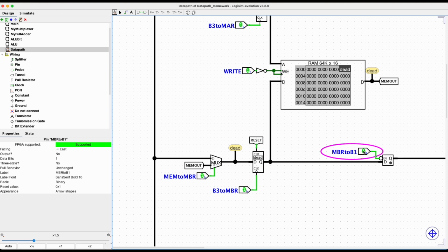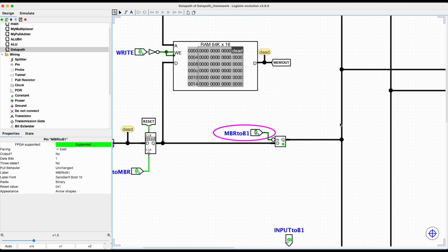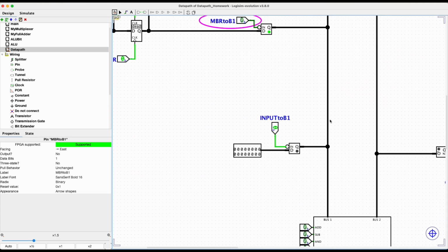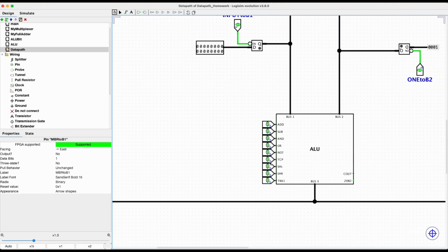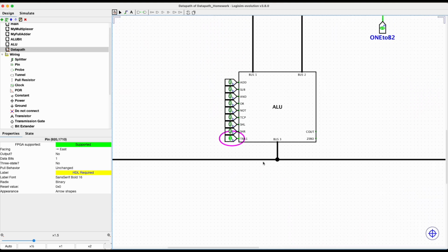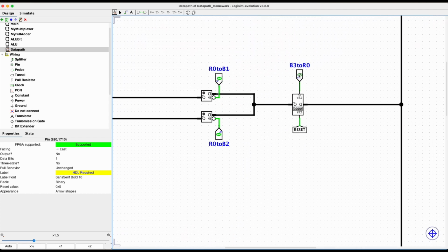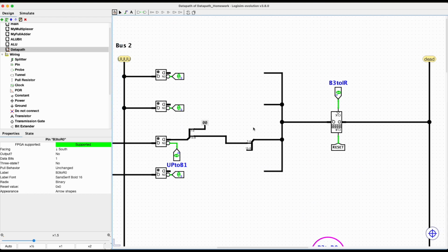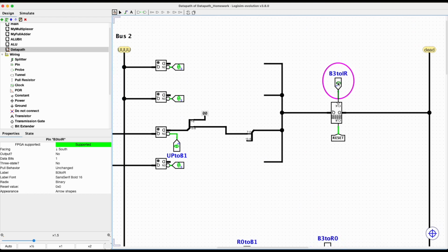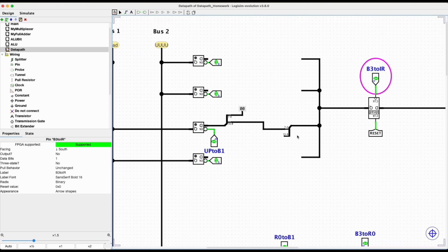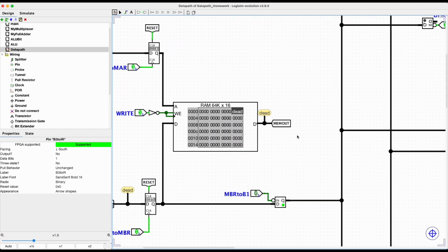We'll put that onto bus 1. So now DEAD is coming out onto bus 1. That's our instruction, our pretend instruction. We'll turn on TRA1, so we got DEAD out onto bus 3. And go ahead and clock that into your registers here. Do it for all 4 to make sure that all 4 registers work. And then last but not least, your instruction register. So now we have DEAD coming out of our instruction register right there. And then we can shut this guy off right there.